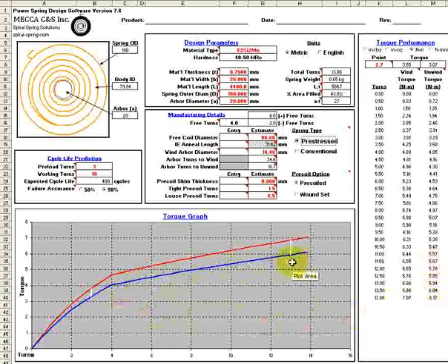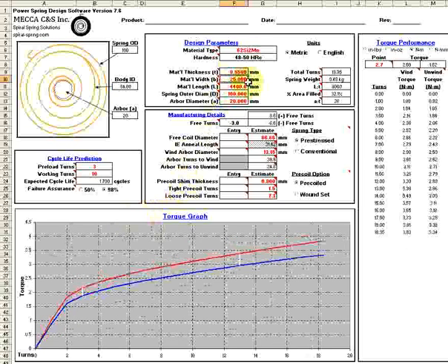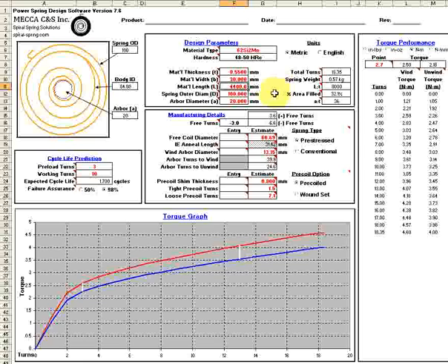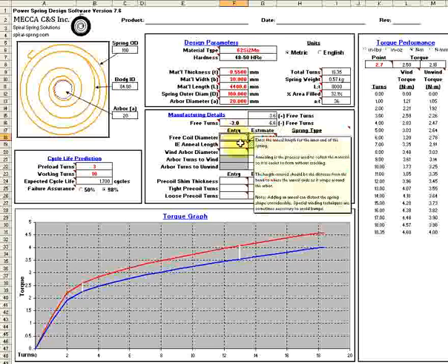The challenge is to make the design meet the required cycles. To get closer to the torque required, the thickness is decreased, the width increased, which is common to a pre-stressed design. Again, review the dead turns shown in the simulation. It gives some indication about the torque and cycle performance. Since the cycles are lower than required, the free coil or shape of the coiled material before backwinding can be increased to reduce stress and improve cycle life.